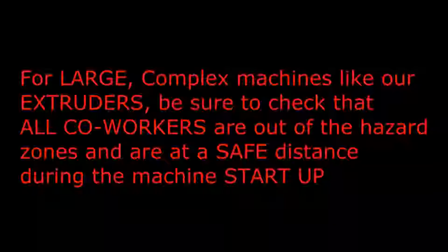For large, complex machines like our extruders, be sure to check that all coworkers are outside the hazard zones and are at safe distances before starting up the machine.